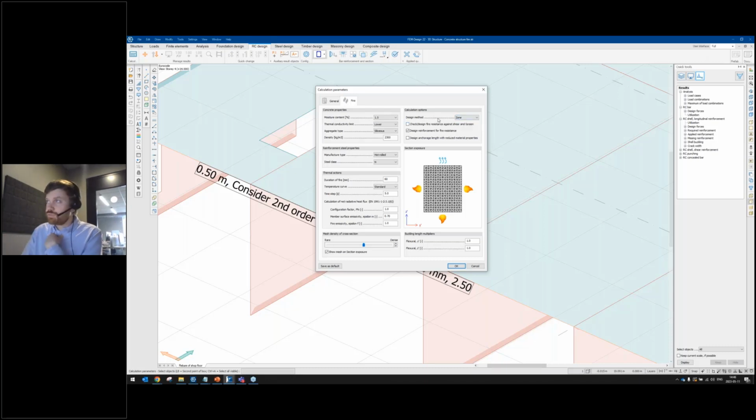However, there is a limitation for this design method, and it's that it can only be used for certain sections. So it's not for all different section types, basically. But for rectangular sections, you can use this method. The other method is a more general method, and it's basically if you exceed 500 degrees, the concrete will be assumed to be damaged and excluded from the calculation. And this method, the 500 isotherm, can be used for all types of sections. But let's go with the zone one.